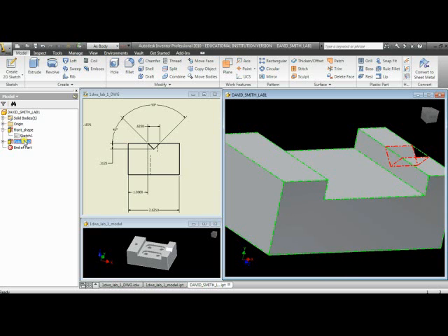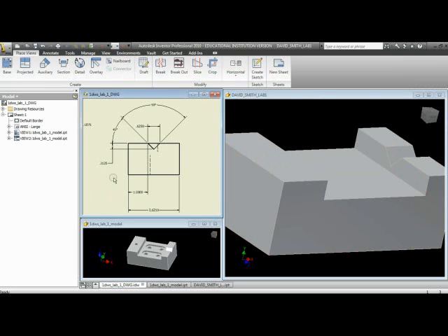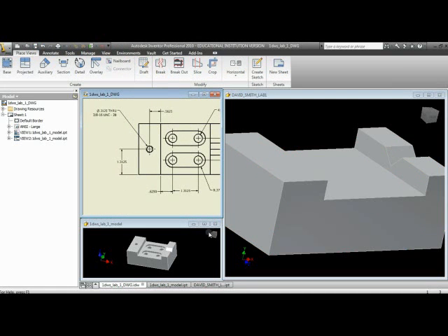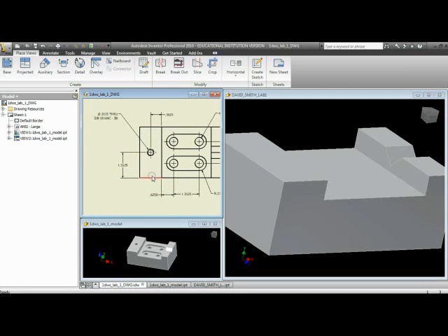Once I've done that, notice the V shape cutout stops right at that location. I can hit OK, and I now have that cut. The advantage here is this. If I go back to this original sketch, which is this sketch right here, and I edit that sketch, and I change, let's say, this 2.6 or 2.5625 to just 2 inches, and I right click and finish the sketch, you'll note that that V shape grew with it because it had to go to the end of this face.